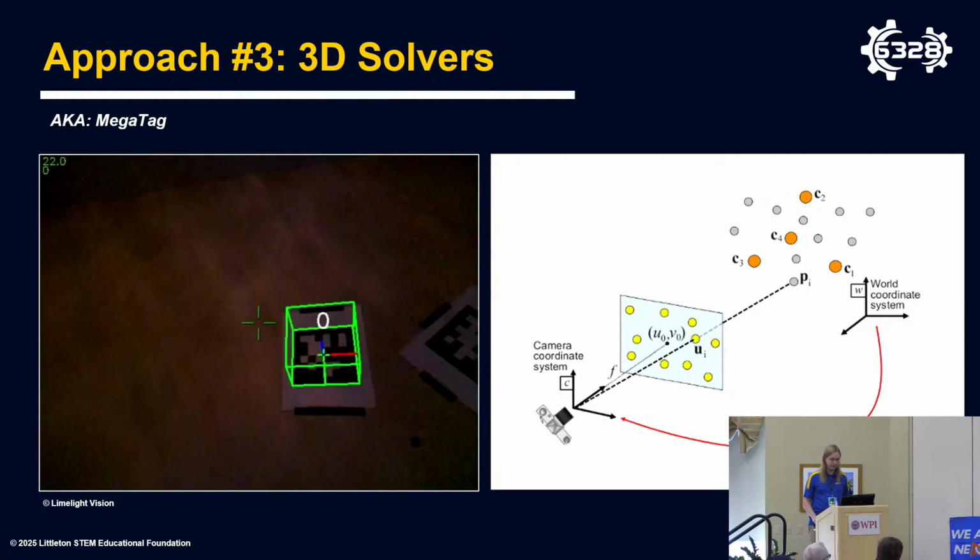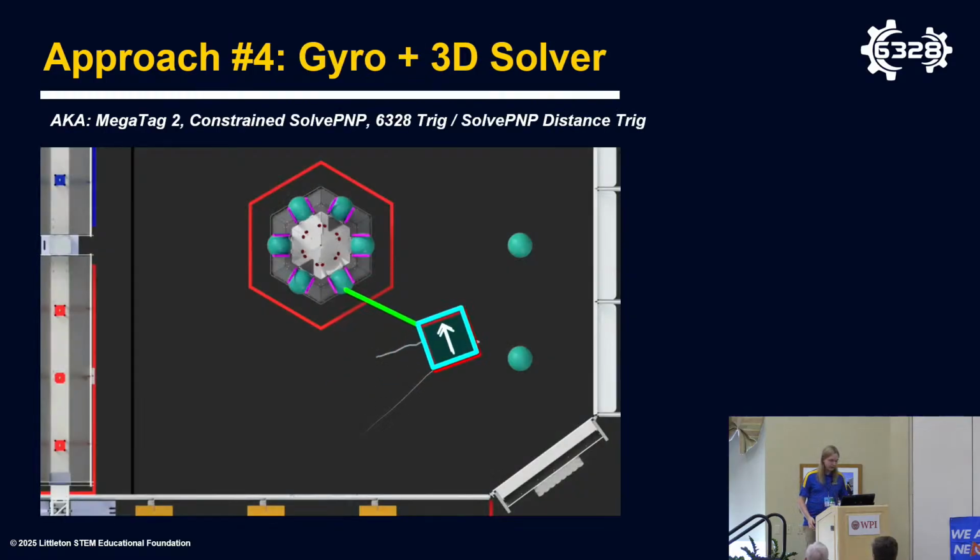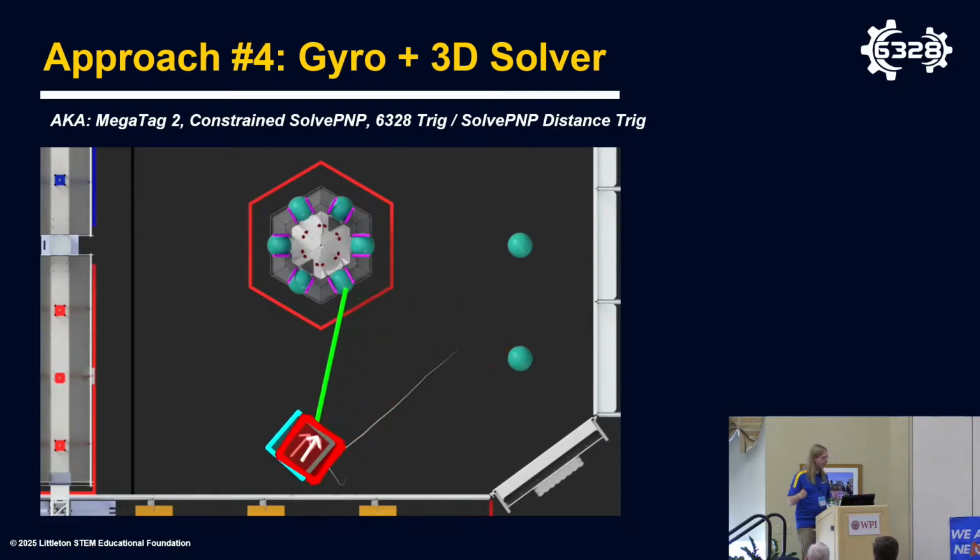Okay, so there are some limitations here, but both are solvable problems that require some additional thought to handle properly. Also to keep in mind, some vision solutions may not actually provide enough data to do that additional filtering well. Limelight in particular doesn't really provide enough data to handle tag ambiguity properly, which is unfortunate, but hopefully will change in the future. But regardless, people started thinking about, as good as 3D solvers are, how can we address some of their limitations, like the additional noise?